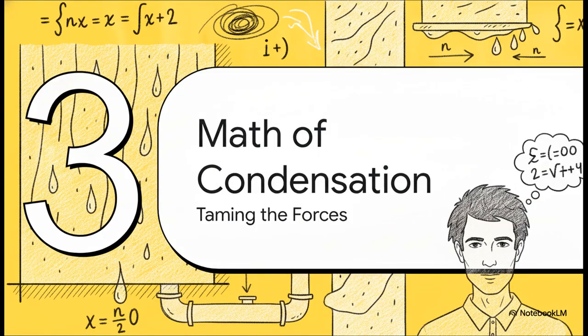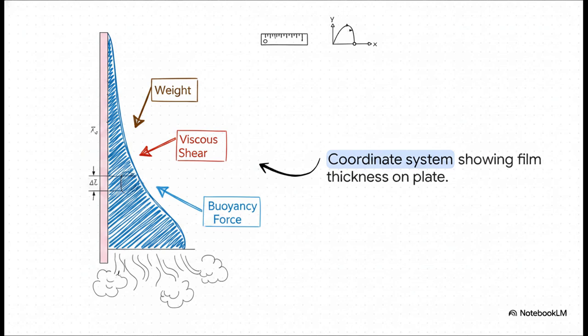Section 3. Math of the condensation film. Because film condensation is the stubborn reality in most industrial systems, we have to know how to predict its behavior. And this brilliantly illustrates the physics first proposed by Nusselt. As that condensation film moves down the plate, its thickness, which is that little delta symbol there, starts to grow. Nusselt realized that the downward weight of this fluid element is perfectly balanced by two opposing upward forces, viscous shear and the buoyancy of the displaced vapor.